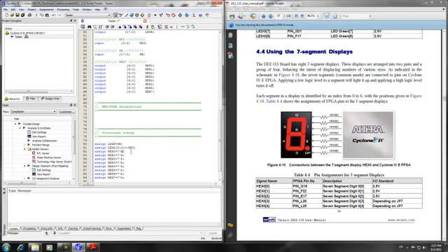We can represent this value by setting hex 0 to 1000000. To display a 1, we'll turn on the connections 1 and 2. To display a 2, we will turn off the connections 2 and 5. To display a 3, we will turn off the connections 4 and 5.